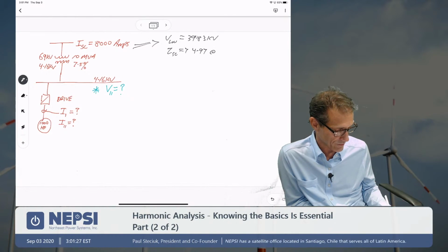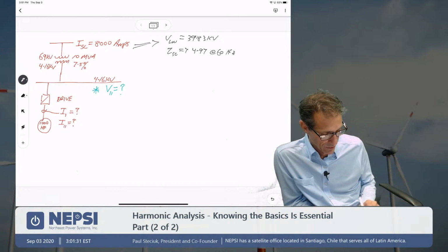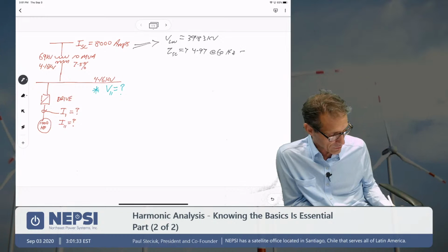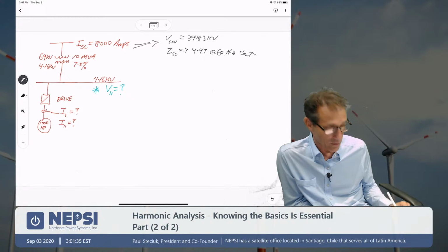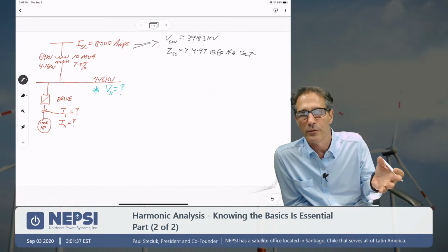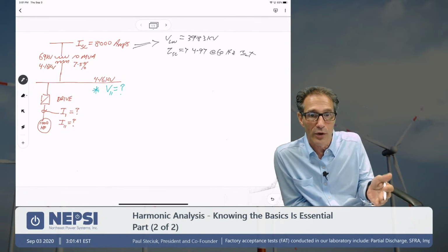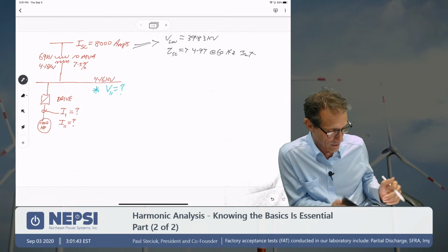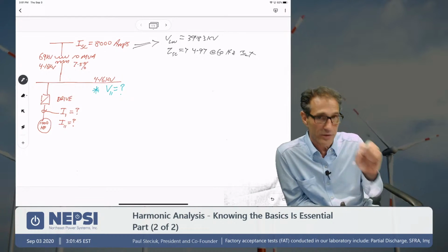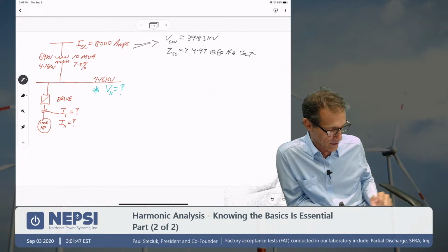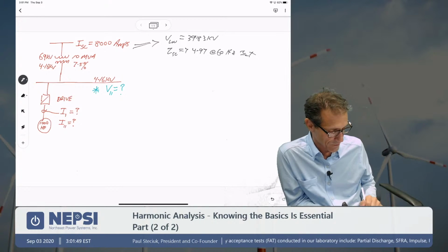And this is at 60 hertz, right? That's about equal to X also. Remember the X over R might be around 10, so we do have some resistance there. It could be 20 depending upon the spacing and things like that. But you're talking about a very low value of R and a relatively high value of X.